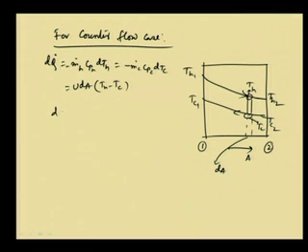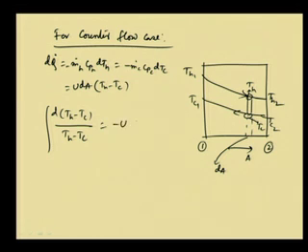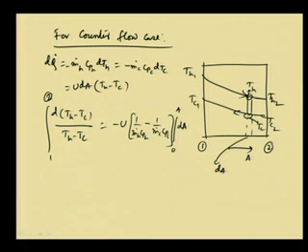So, then we can get Th minus Tc, and in this way now we can write d(Th minus Tc) by (Th minus Tc), as we have done previously in a similar way. If we do this here, we will get it as minus U into 1 by m dot h Cph minus, it will be minus here, 1 by m dot c Cpc into dA, and this integration will be 0 to A, and this is station 1 to station 2.